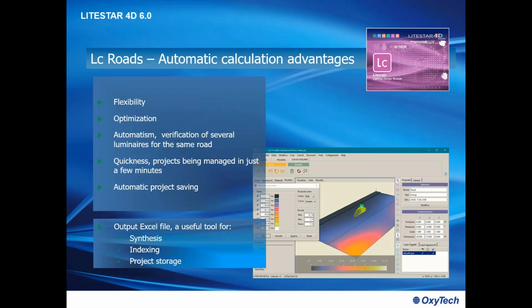And I'd like to add that we don't have only information related to the design, let's say to the road calculation, but we also included information related to the luminaire with all the different parameters, such as, for example, the American BL and BH coming from the IES TM15, the so-called BUG, or, for example, the G asterisk, or the D coming from the European standard 13201 related to road lighting, etc. So in a single Excel spreadsheet, you really have all the information you may need, and they can be analyzed in a very short time.